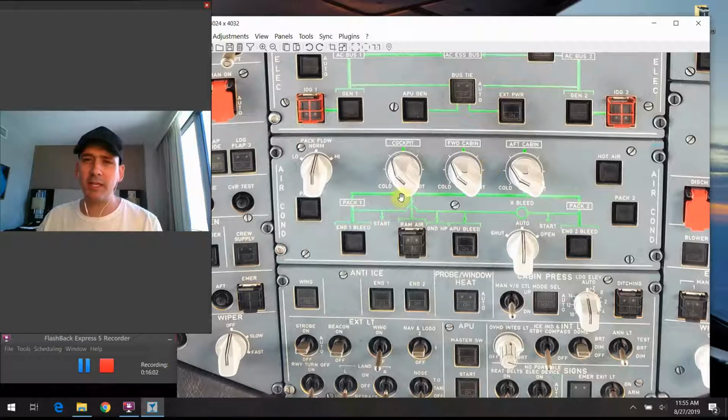But very specifically, it's a range of 18 degrees Celsius to 30 degrees Celsius, and right at the top, the 12 o'clock position is 24 degrees Celsius. And you just kind of get used to where these knobs tend to live. I can just tell you guys, for very general purposes, the cockpit knob usually stays at about the 12 o'clock position, and then at least when we're cruising around, anyways, in the forward cabin, the aft cabin usually stay somewhere around the 10 o'clock position here. It just seems to be what's generally normal, nice, comfortable temperatures that everybody likes to be at. So those are what those knobs do there.